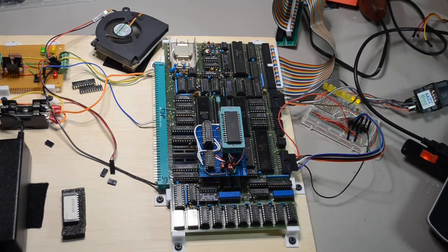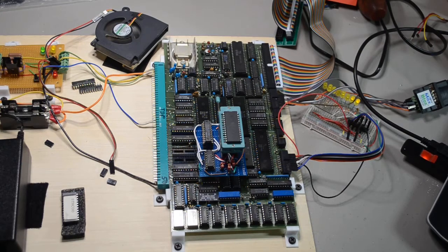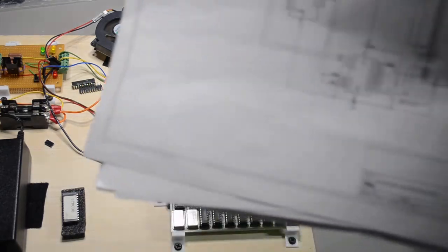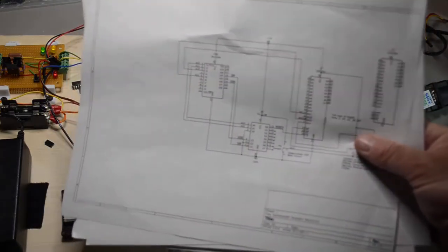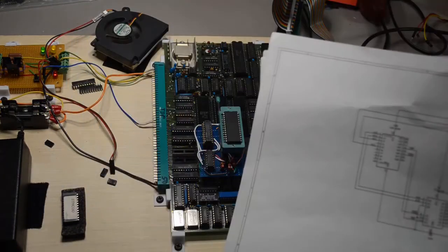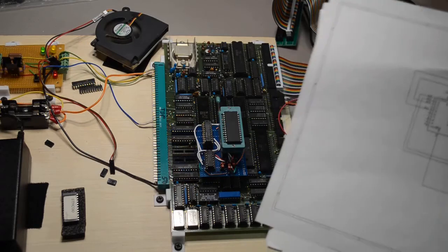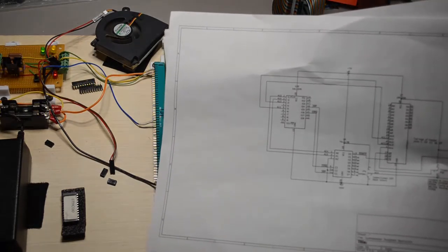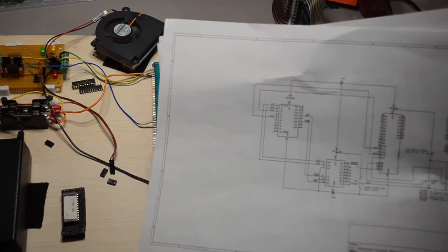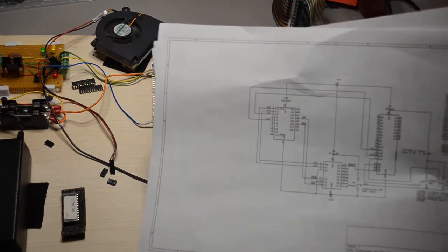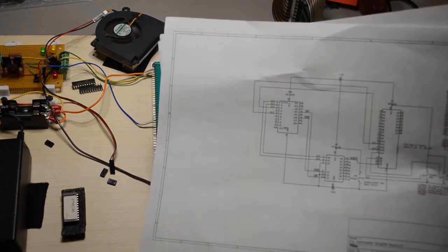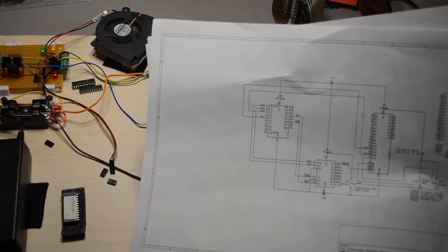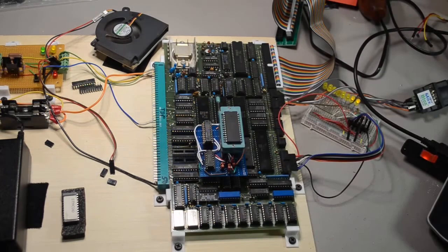Basically, I just reversed a couple of wires coming off of the address decoding chip, the 74LS138 down here. It didn't work, and I went through it and double checked everything. There's the reversed wires. Okay, that was the problem. So that was really the only hardware issue I had. Well, the only electrical design issue. I had some mechanical design issues.